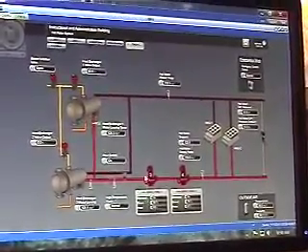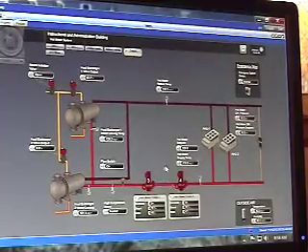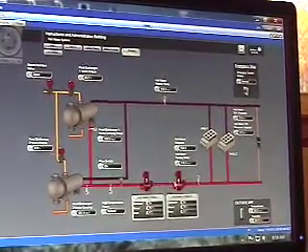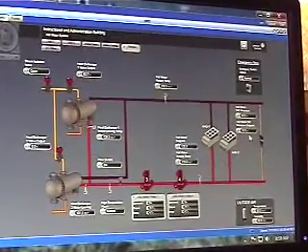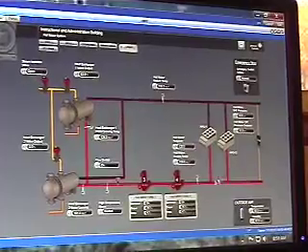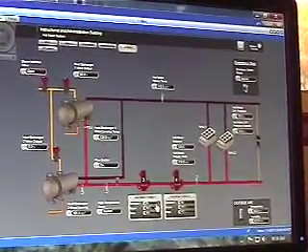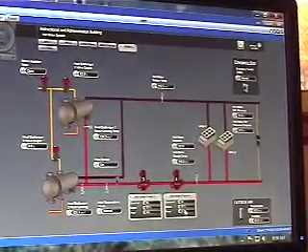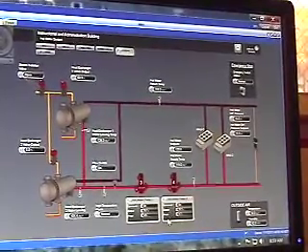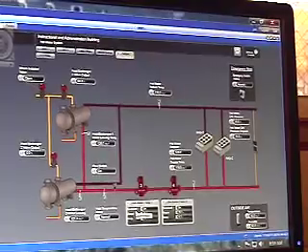Pumps right here. These pumps will run together quite a bit of the time. It looks like that's what they're doing now. These pumps are controlling to maintain differential pressure set point. It looks like it's 18 pounds. As that goes up and down, if your pump gets above, I'd have to look at it, I thought it was 70%, we'll call for lag pump. When it gets below 35%, the lag pump will drop off.